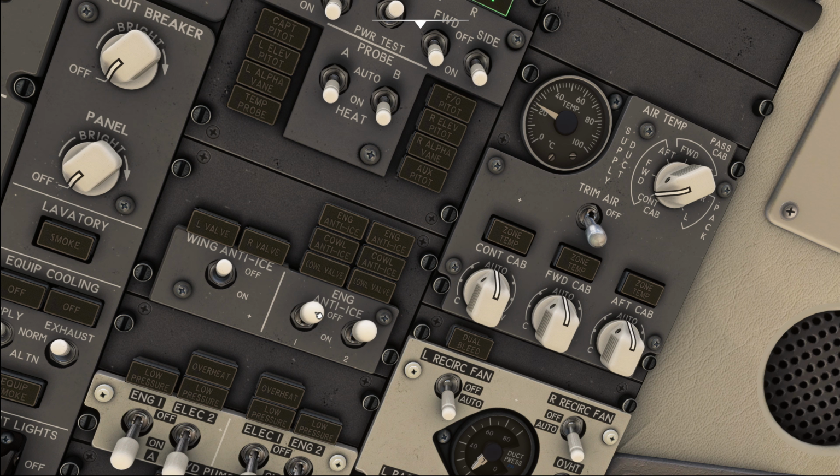Remember, when you previously turned on the engine anti-ice on the 737NG, you would get the blue lights illuminating first bright blue, then dim blue, and the dim blue would indicate that the engine anti-ice valves are now open. Now this is no longer the case on the MAX. The MAX follows the dark cockpit concept, so when the switch is operated, the light comes up as the valve position disagrees with the switch position while the valve is in transit, but as soon as the anti-ice valve is opened, the light simply goes off to indicate normal system operation.